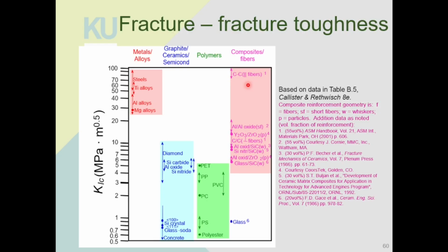Okay, what is the importance of fracture toughness? It is the material property that you need when you want to choose a material that can withstand not just impact but repeated impact and repeated applied energy without breaking. So, for example, if you choose a material for, say, a root canal, you can choose either metals, ceramics, or polymers. You can see that metals have higher fracture toughness. That means they can withstand the repeated action of chewing without breaking, right? But if the screw for the root canal is made from ceramics, it can crack quite easily because it has low impact and low fracture toughness.